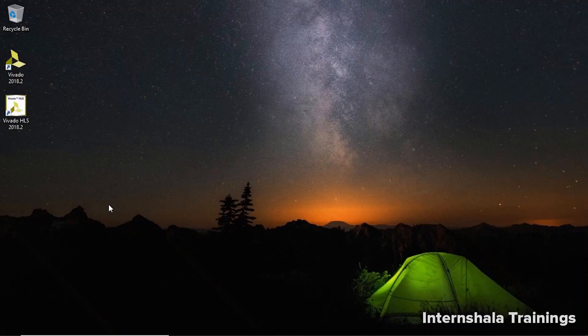So as we had discussed in the installation video, you will be getting two icons. One is Vivado HLS and one is only Vivado. You have to click on Vivado. Double click and wait. It will take a few seconds to load. Do not click again and again because it will open multiple instances of Vivado. So only one double click and then you have to wait.